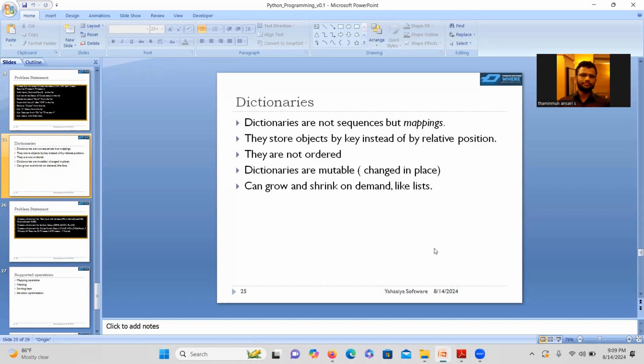That will be a very perfect match when you are using Python for simulation development or network analysis. At that time, you can use dictionaries as a replacement, an alternative for your CAN database. You can define the signals as a key and the numerical value associated with that signal as the value. In that sense, dictionaries will be helpful for automotive testing.